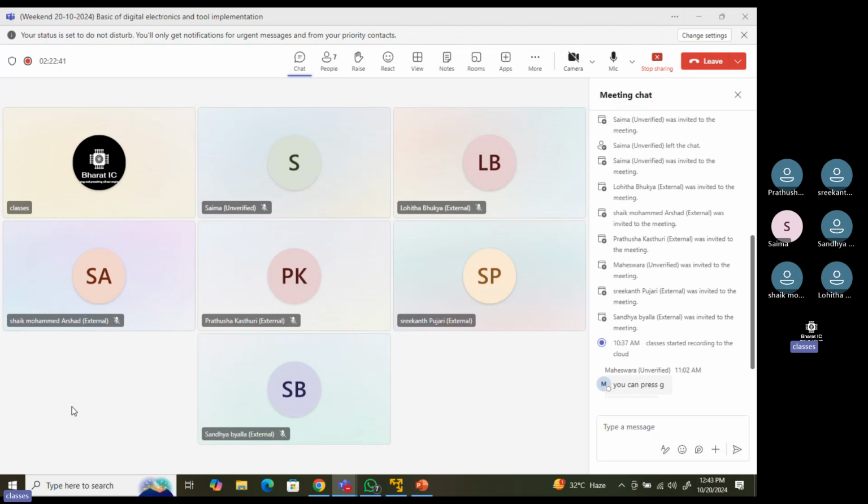So you have to use M3 or M1 or any other metal other than M2. Then only you can pass it. Signal A and signal B can cross each other at a junction point, like a plus symbol.